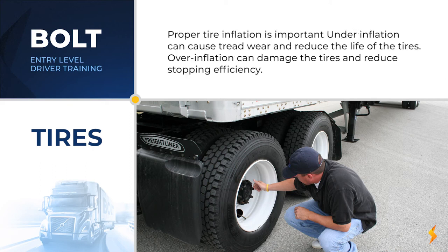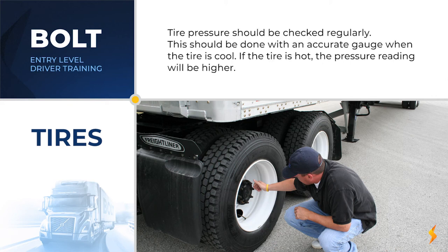Proper tire inflation is important. Underinflation can increase tread wear and reduce the life of the tires. Overinflation can damage the tires and reduce stopping efficiency. Consult the vehicle's owner's manual for inflation guidance. Tire pressure should be checked regularly.